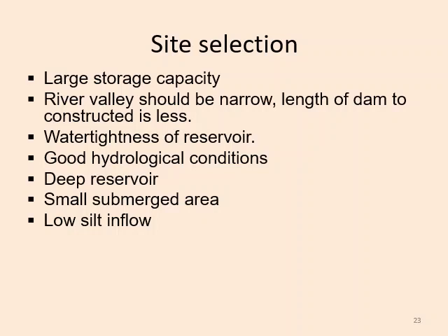The river valley area where we will construct a dam and reservoir should be narrow. That means the width of the river should be narrow, and the length of the dam which is to be constructed should be less. Water tightness of the reservoir. Good hydrological conditions.